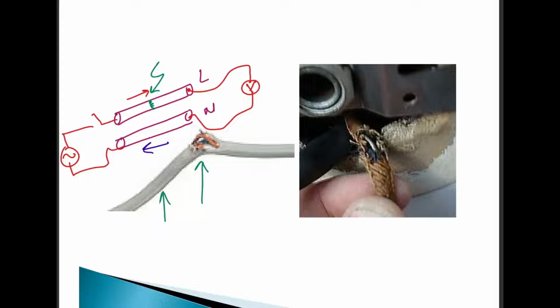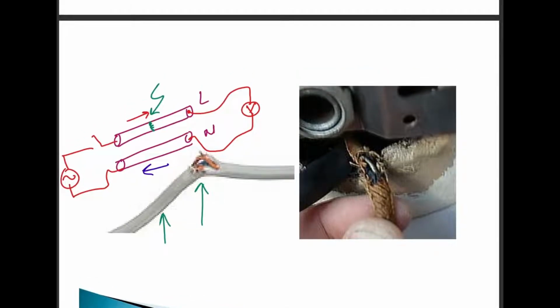And why do we say that there is a thermal limit? If this wire is designed to carry 2 amperes of current, and you demand 10 amperes of current through this wire, it may be able to sustain it for a very short amount of time, but very quickly it will heat up and eventually melt, which is going to cause a short circuit.